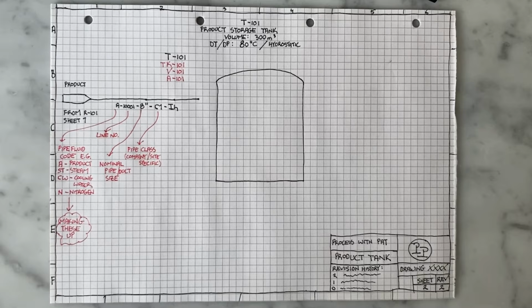So it's useful because you can say something like, oh, you're transporting steam. Usually we use pipe class X, but we can also use pipe class Y to convey steam as long as the temperature of the steam doesn't exceed so many degrees. Apart from the pipeline material itself, the pipe class also describes which valves and flanges and nuts and bolts I'm allowed to use. It's quite a detailed thing to go into, so don't worry about it too much. And if you're submitting a P&ID for, say, a university assignment, you can't really be expected to even know this. So this is just for information.